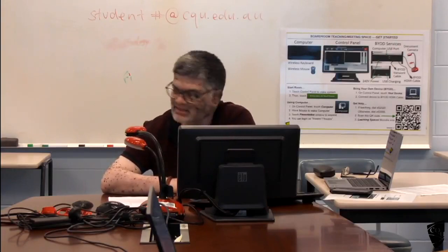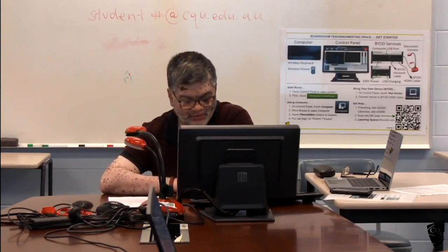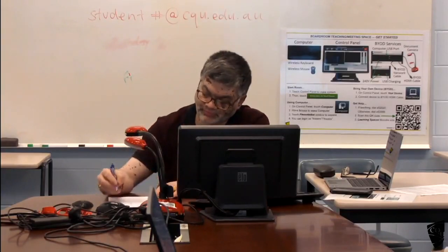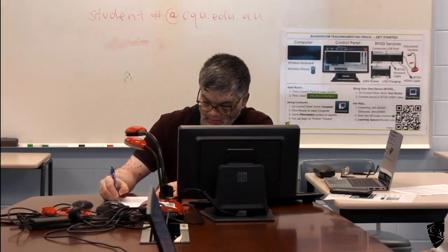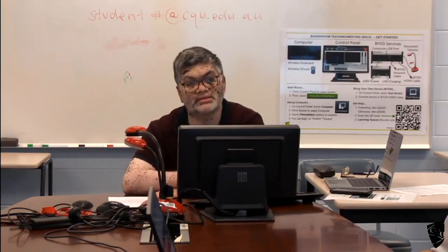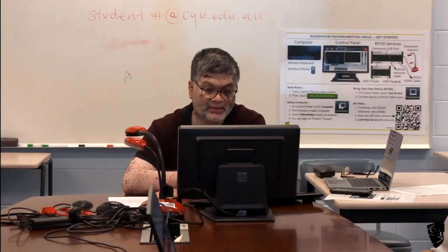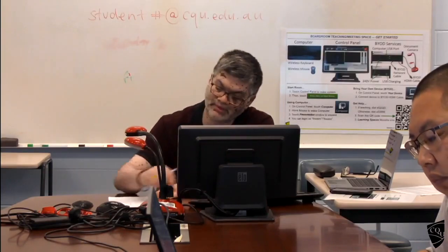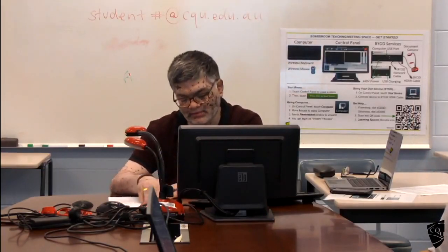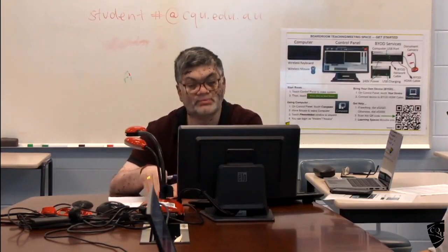So in this case, what we do is we use strip method. I put all these details there, but I just explain step by step what to do. So strip method means we divide this slab into strips.